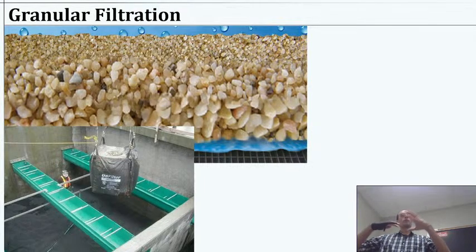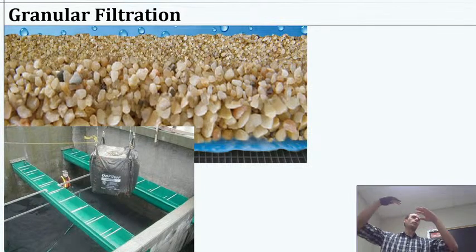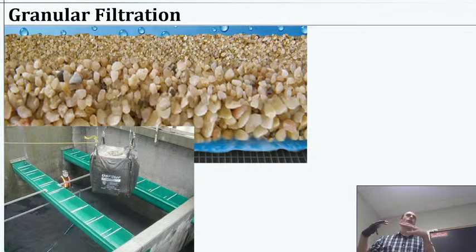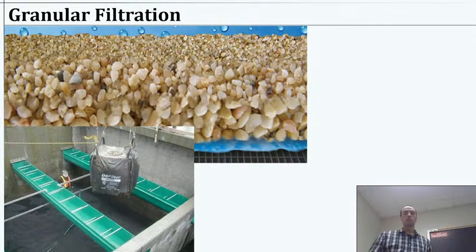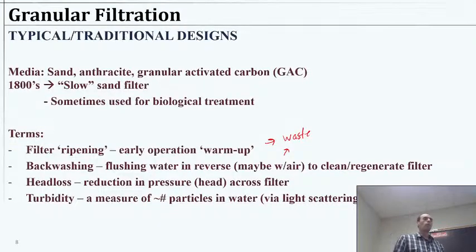And as there becomes more resistance with more particles stuck around in there, you naturally need more force to push the water through. And so you'll add water at the same rate. Let's say, for a few filters, maybe 1 million gallons per day, constantly all day. But as they get clogged, the water level will rise, pushing more force through them. So it's a nice natural way to stabilize your flow rate. You have a continuous flow rate over time, because as your head loss rises, your water level is just going to rise with it to account for that. Okay, so that's what we're talking about when we say head loss.